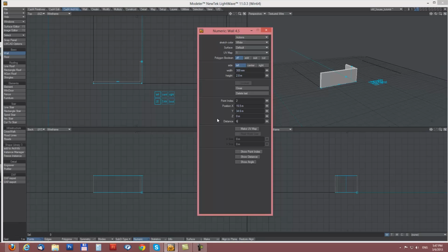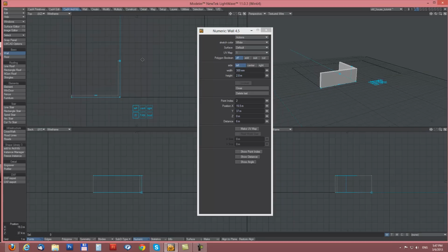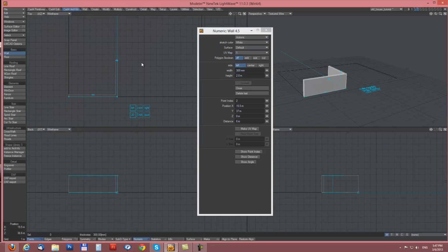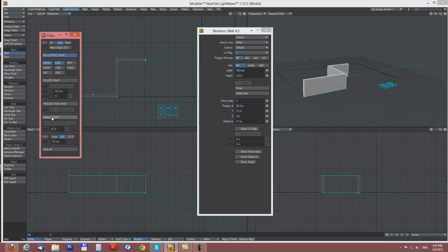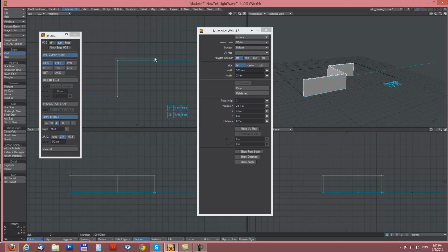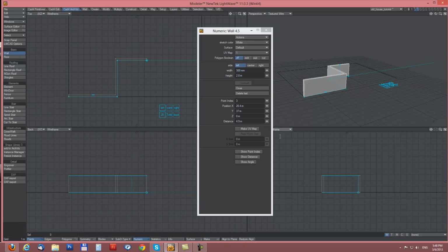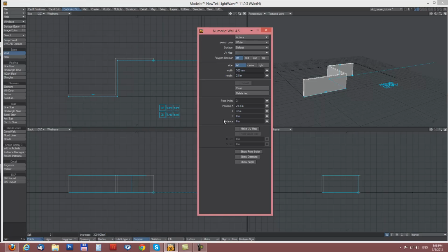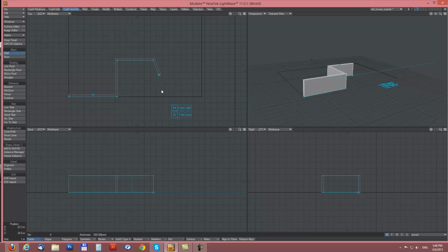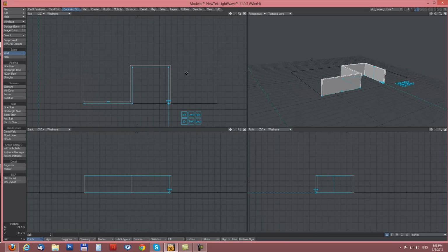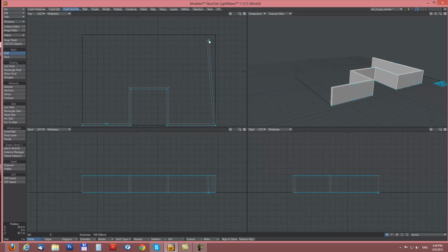will be a 6 meter segment. Also a big helper is when we hold the Ctrl key on the keyboard, you can restrict the segment angle to 90 degrees. If you need a different angle snapping, you can use angle snap in the snap panel, so you can use 45 degree snapping. So let's continue now with segments. Distance again is 6 meters, and for the rest I will just use snapping to the boundary line in the background layer.